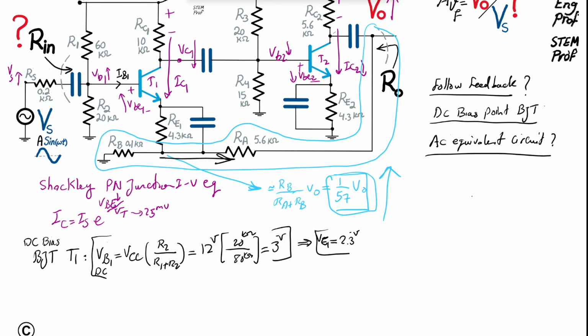So it's a large resistor we are looking at. So what I'm trying to say is this 0.1 kilo ohm, when we look from the perspective of this emitter downward, is much, much smaller than whatever we see in parallel with it. So I'm going to neglect these large ones. And I can make the assumption that for DC analysis, RE1 and RB are effectively in series.